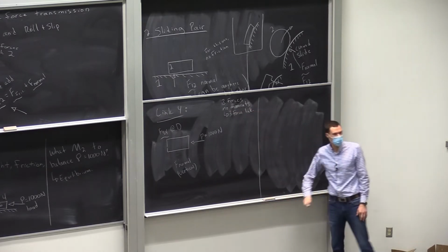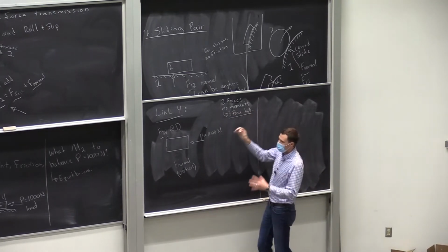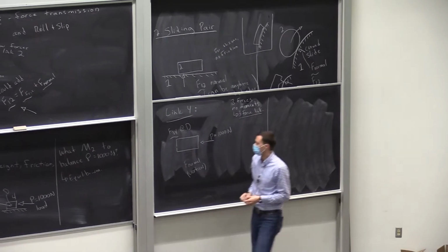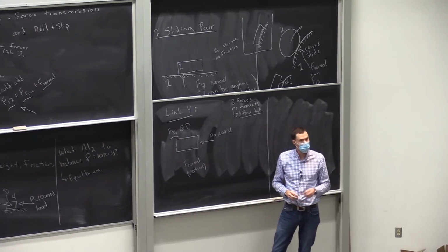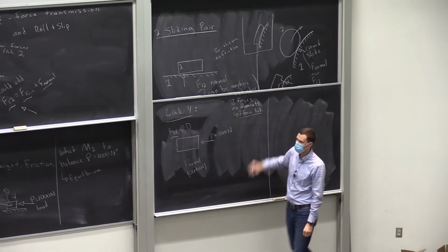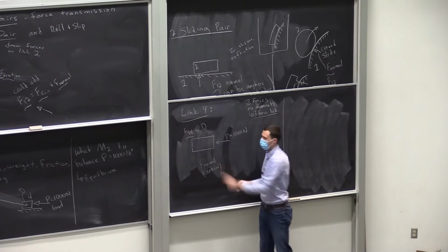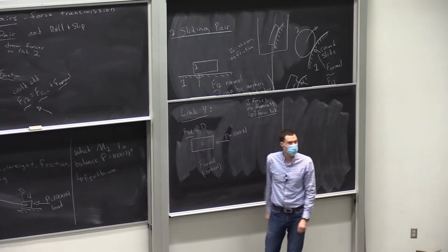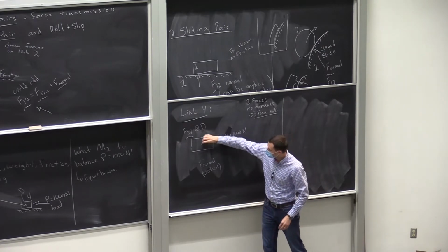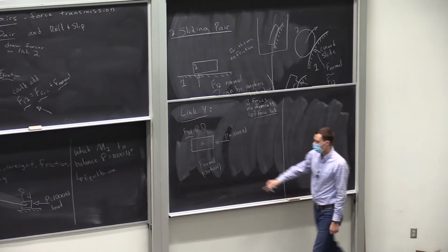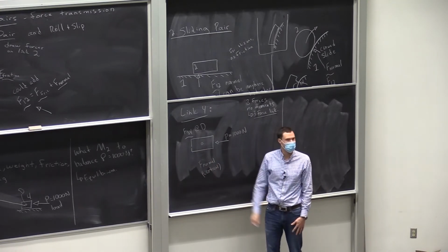So you're going to be the detectives as you solve these problems, and you're putting together all these clues. 3-force link, we can go into 3-force link mode and say, okay, all these forces need to intersect at a common point, right? Common intersection point for 3-force links. This is good. So 3-4 is at D. D is right there, right? P is right through the center, also pointing at D. So right off the bat, we know F normal should also point at D.